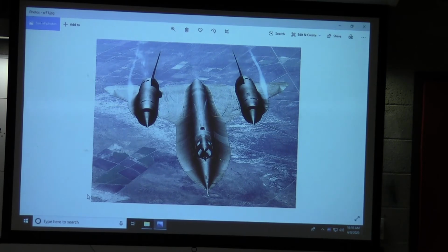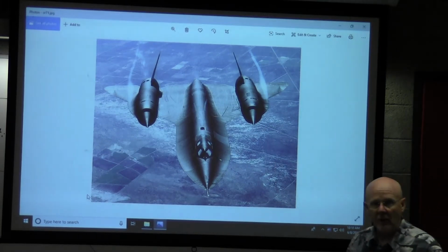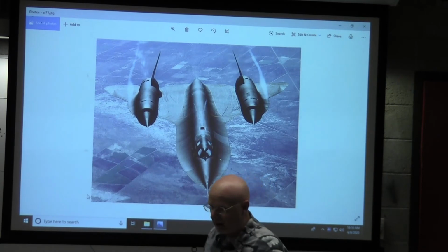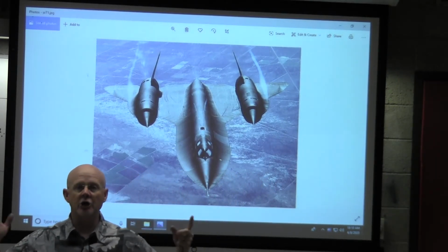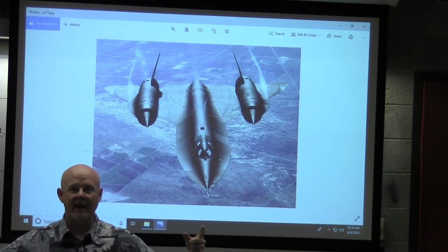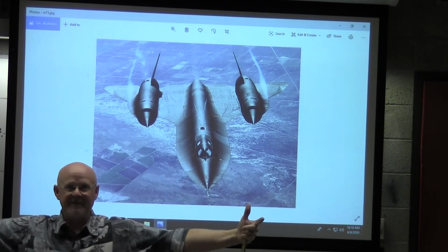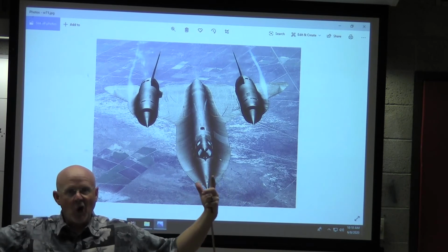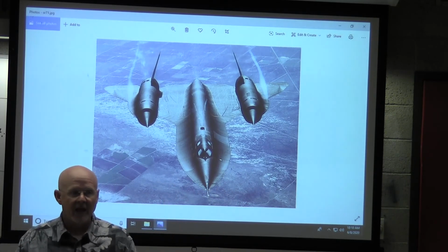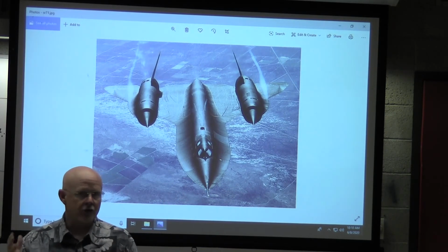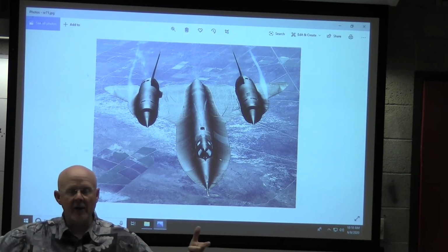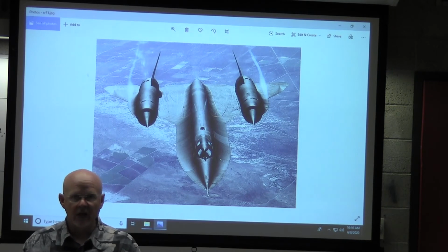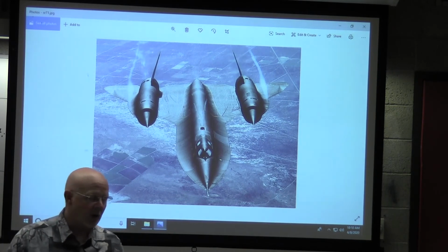And then the engineers realized a challenge. They're saying, ooh, how do we contain the fuel? How do we deal with this expansion? Because this airplane is 108 feet long when it's on the tarmac, and when it's in flight, it's 109 feet. It gets a whole foot bigger. And so the control rods that control the surfaces, how do you do that when the surfaces get further away depending on how fast it's flying? How do you account for all that? And so all of that was a challenge.